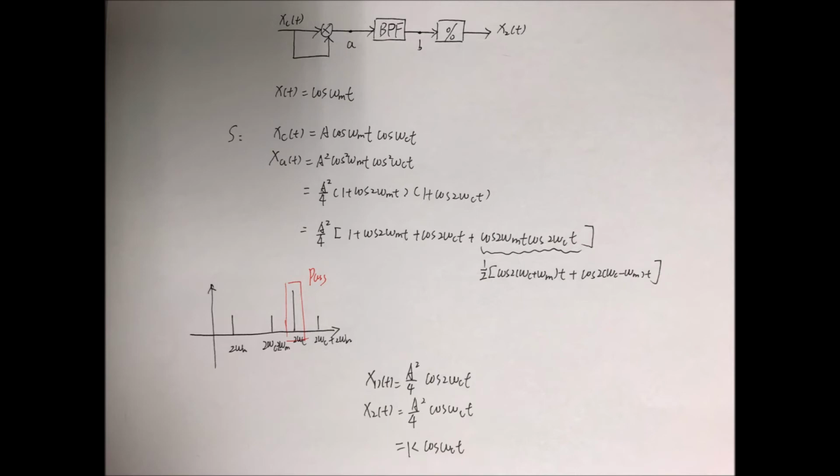This is for 0. So people developed what is called Manchester code. For Manchester code, you have a high then a low for bit 1, low then high for bit 0. So in this case, no matter how many continuous 1s or 0s I have, clock is still built in. Every bit, you'll have clock information. Right, so extracting a reference from your signal is very popular.